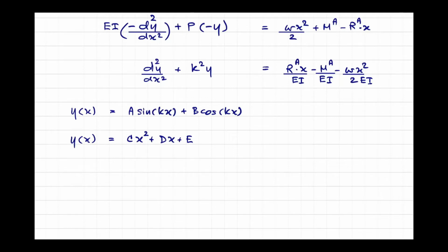And then if you use the program and say, oh, this structure is going to be okay, the assumption is that C and D will not be significant, and you can just omit the effect of C and D. So you need to verify that C and D are really negligible. It is dangerous to use the program without knowledge, without any concern about the actual condition of the structure, right?